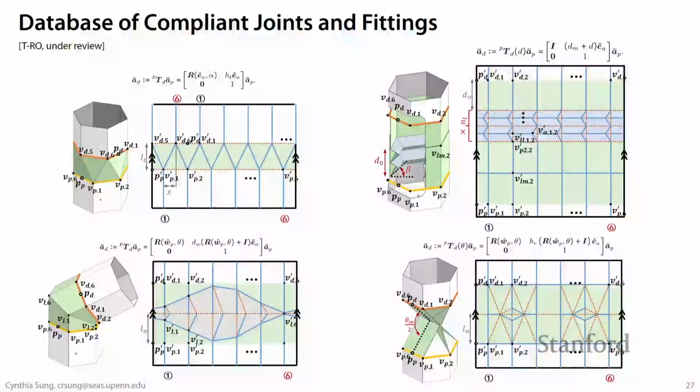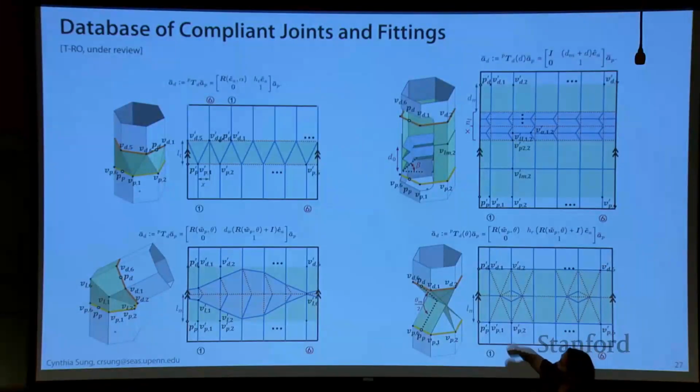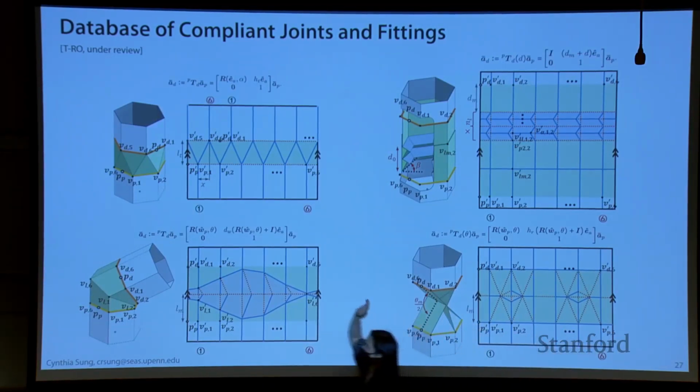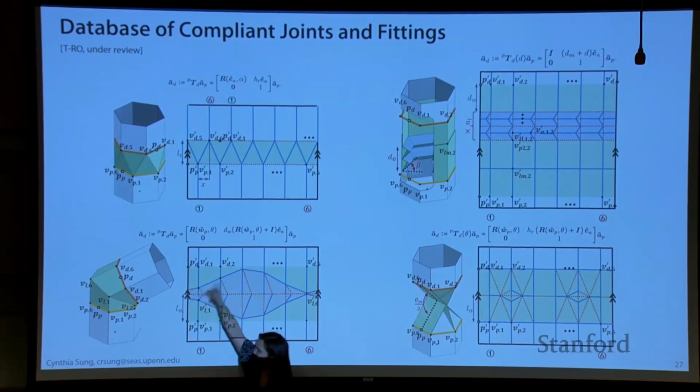Yes. So it is actually origami. And so the prismatic joint is based on the bellows that I started with, where you can compress it, and then we added in these walls on the side to constrain the motion so that it doesn't bend. So this is still folded out of one sheet of paper. It's just kind of folding back on itself. And then here's the revolute joint. And then these 2 modules over here are our rigid components. This is for the circular arc, and that's for the translation.